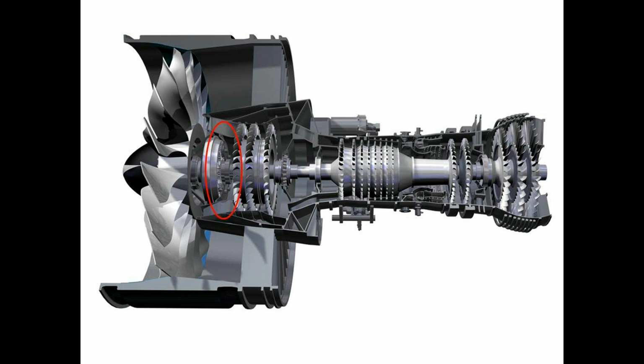The air passes through a series of stator and compressor stages, which compresses the air into a smaller volume, while accelerating it towards the diffuser. When the air is passed through the diffuser, the gases slow down in exchange for an increase in pressure while entering into the combustion chamber.